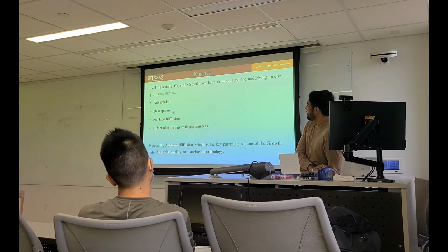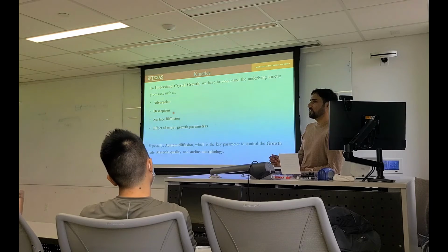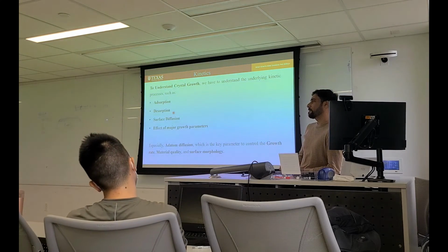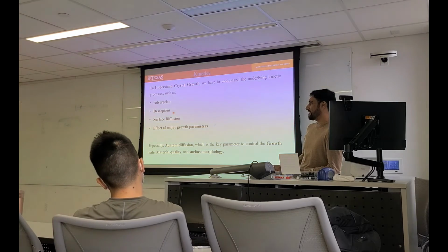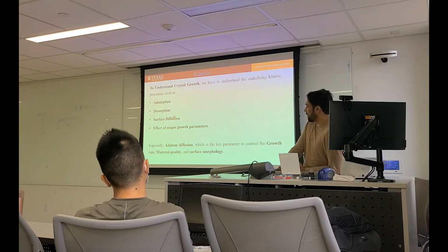Kinetics: to understand crystal growth, we have to understand it. Now here I am just talking about how we can tune the growth conditions. Even with ALD, with sputtering, with CVD, with any technique, if you know these things, you can control your morphology, you can control your strain. The fundamentals are adsorption, desorption, surface diffusion, and the effect of major growth parameters. I have talked about these three things.